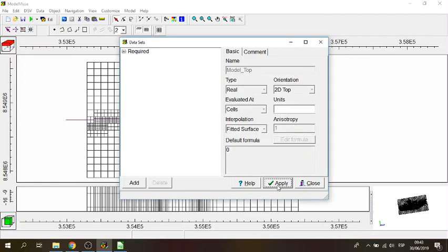Okay, that's great. Another thing that you might need is that we are going to do a progressive thickness between model top and lower aquifer bottom. That means that the first aquifer will have 15% of the total thickness, and the other will have 35%, and the other will have 50%. There is a formula for that. I won't go into the definition of the formula, but if you see the formula and then you put some numbers, you will get the purpose of the formula.